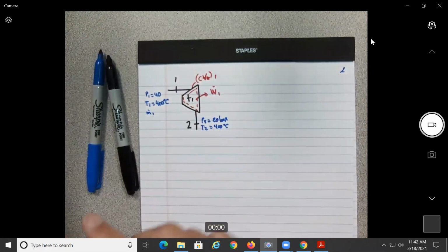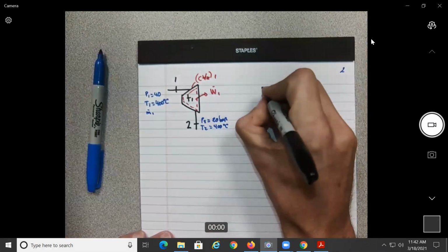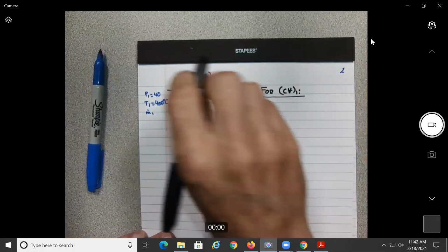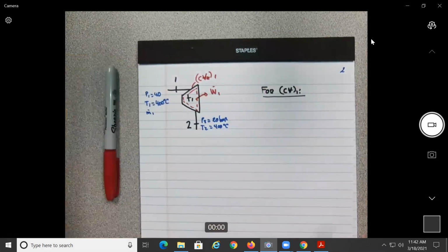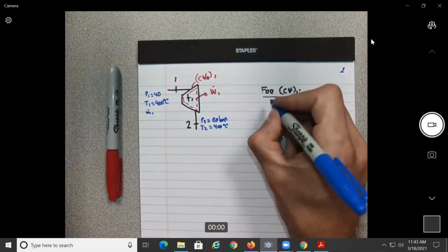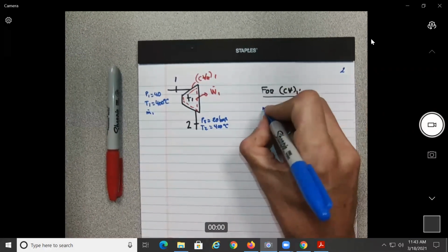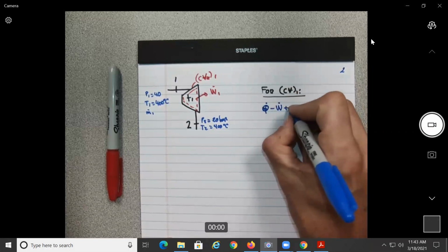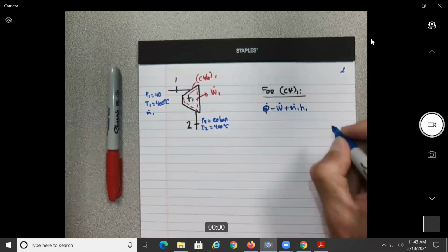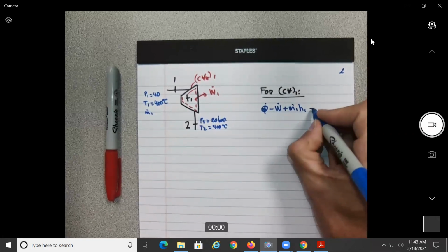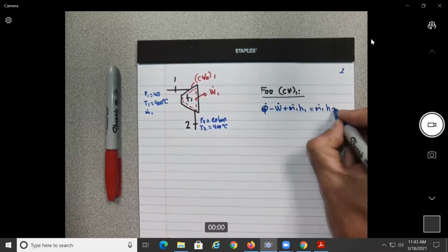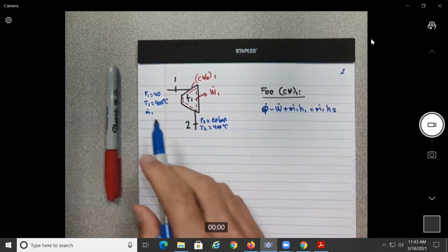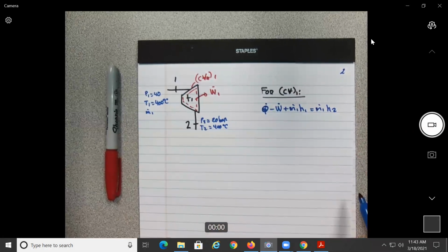So for control volume 1, again, I'm going to use the blue because it's brand new, so it writes much better. So what do you have? We're going to have Q dot minus power plus M dot 1 H1 will be equal to M dot 1 H2, because it's conservation of mass flow, no? The M will be the same everywhere, no? Okay.